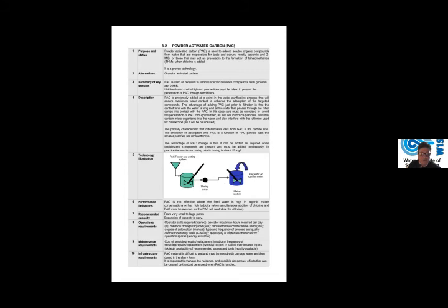Like for instance, the Cape Town waters, certain times of the year, they have lots of taste and odor problems in the water, and then they would dose powder activated carbon. But once that outbreak is stopped again, then they don't need to dose the PAC, and you can just not use that anymore until the next incident.